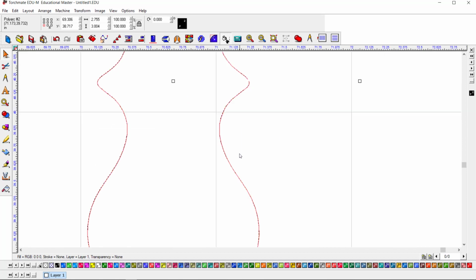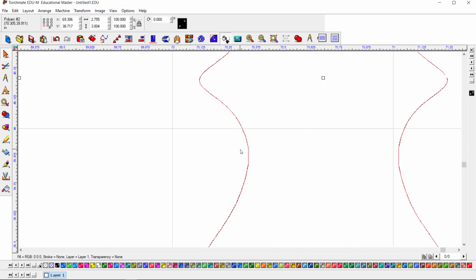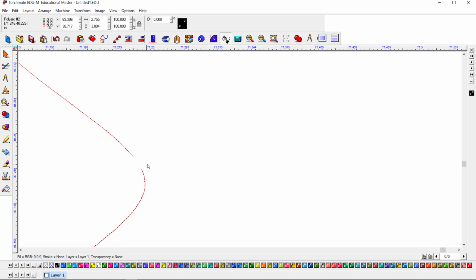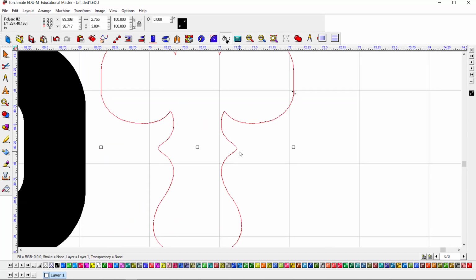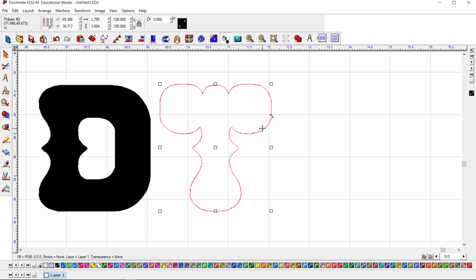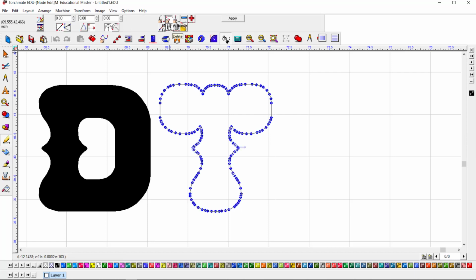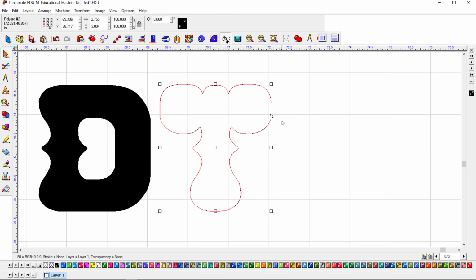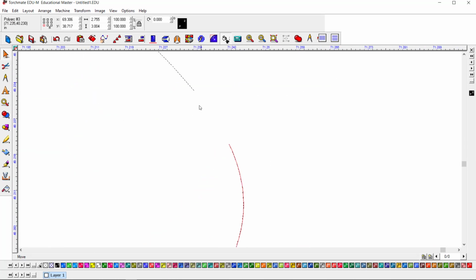So a trick that I use is I'll scroll in like this as much as I can. If it's obvious, like, oh, I saw it right there, I'll just fix it. But if it's not obvious, I'll just double click. I'll come in here, I'll just delete another segment and I'll break path. And then I'll go, oh, see how it highlighted? I know that there's a break here because I put it there. See that? But see how it's red up to right here? Now I scroll in there, oh, there it is.